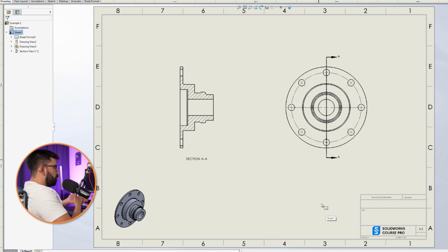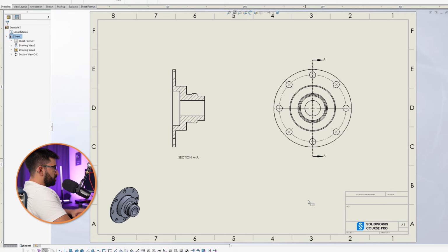Make sure you're following the alphabetical order. Otherwise, if you start with C and your drawing is too crowded, people would have a hard time looking for the A section and the B cross section, and since they don't exist, it would be super confusing. Pay attention to these details, okay?